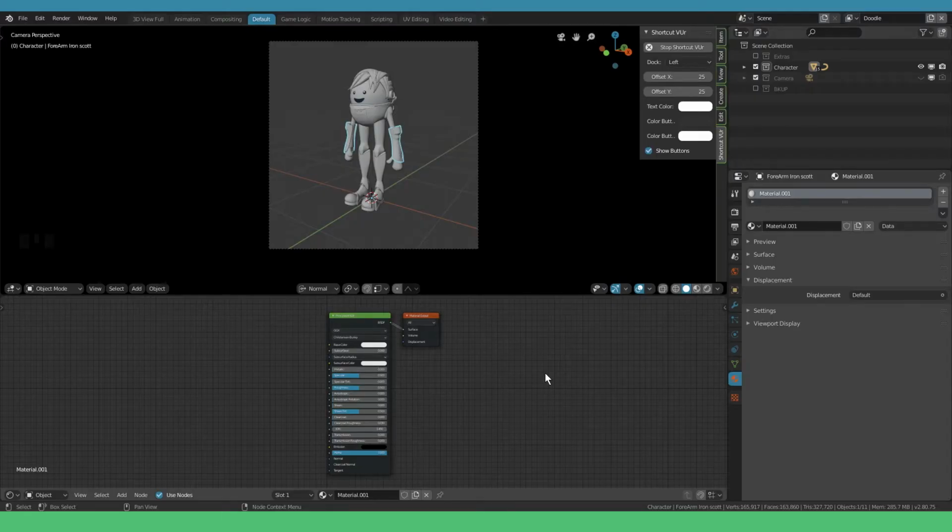Okay, moving on. Right off the bat we get the default principled shader, also known as the Uber shader. This shader is pretty much all you need in 90% of your work. From here you can build up realistic and complex materials. But first, let's take a step back and try to block in our flat colors. We're doing this to see if our color scheme is working on the model. I like to start with a simple and clean emission node. Delete the principled shader for now.